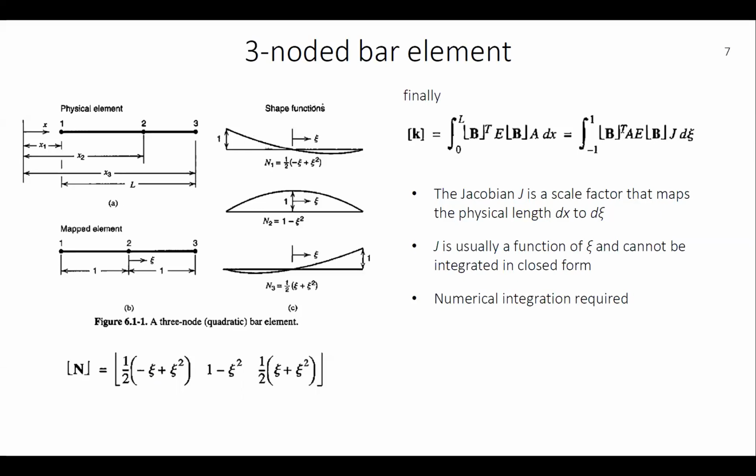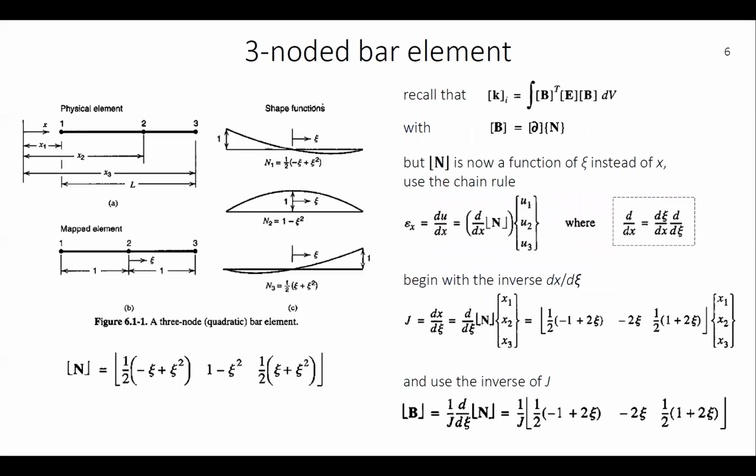I don't think there will be a denominator singularity problem when we integrate this system. I mean, it could be if the nodal points are positioned in a very awkward way. So typically, if node number 2 would be outside of the element or not bounded in between node 1 and 3, then you will have a singularity.